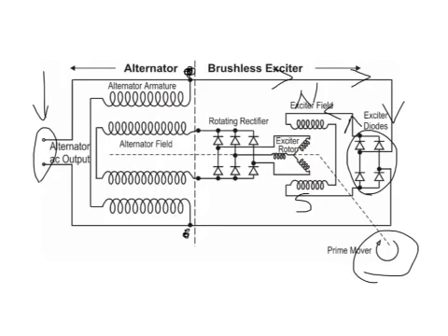So at this point, current is flowing through our exciter diodes, creating a bigger north and south pole, which of course gives us our lines of force in here. And as this prime mover turns the exciter rotor through those magnetic lines of force, that induces an AC voltage onto the exciter rotor. That AC voltage then, which is essentially an electrical pressure, is going to cause AC current to flow out to our rotating rectifier.